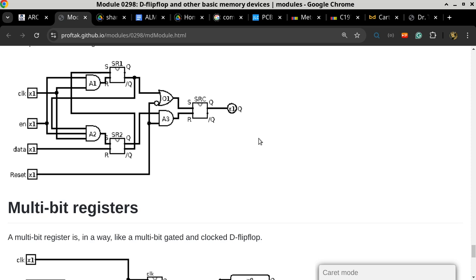Some need to be hit every 2 seconds or less. Other ones may need to be hit every 5 seconds or less. Basically it's a dead man switch. If you don't hit the watchdog within the specified period of time, the watchdog is going to reset the whole thing. It will activate a reset signal, which is the reset pin here.